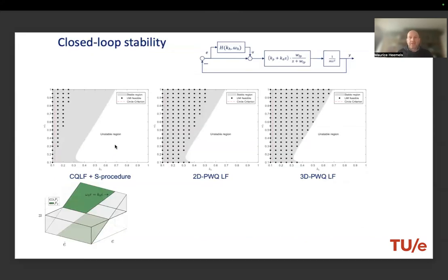Right, a short example. So what do we have here? We have a mass, so just a double integrator. So just a mass being shifted around. We have a low pass filter over here. So this is a low pass with PD. And so we have this configuration. We have HIGS actually added in this configuration with the two control parameters, which is the K, the sector that describes the sector, and the omega that describes the integrator frequency. So that involves the internal dynamics of the HIGS.